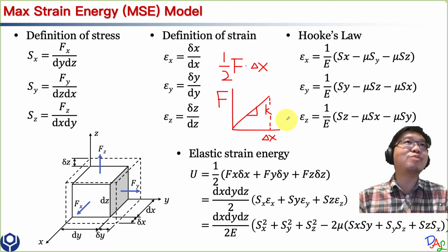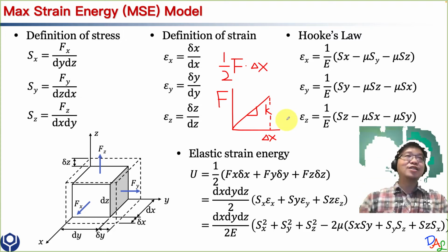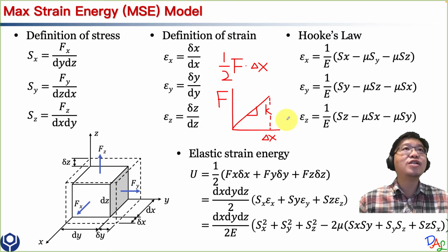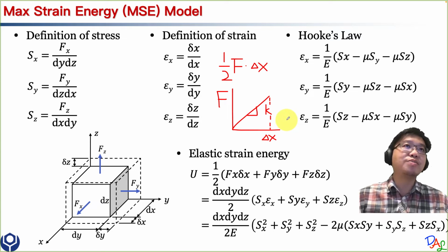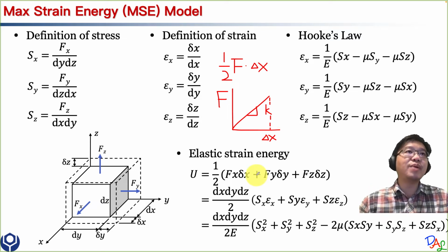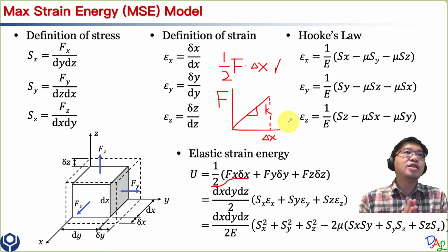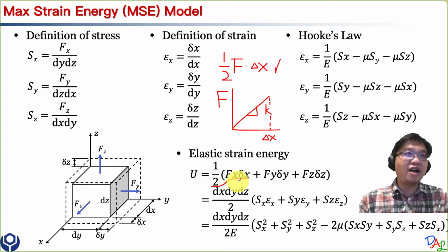I couldn't explain well when I didn't have an equation and figure right there, but now I have it. We treat a material like a spring, and the strain energy is the integral right here, so 1/2 of the force multiplying the deformation.